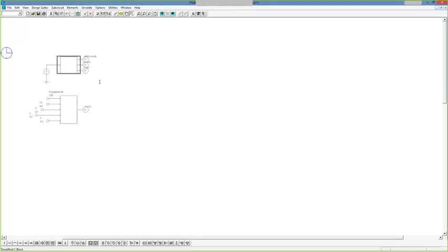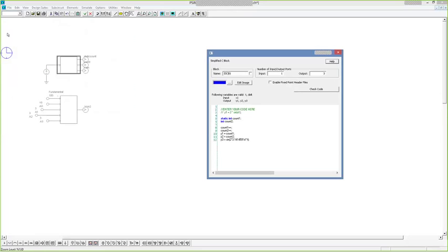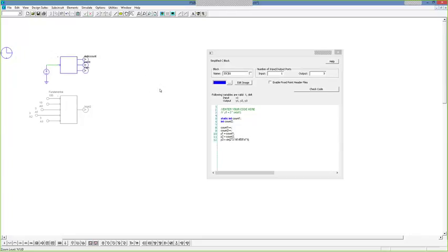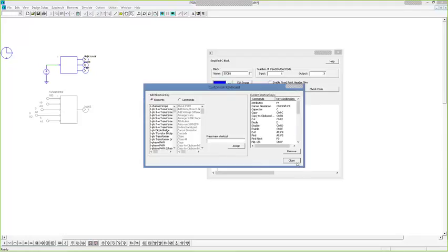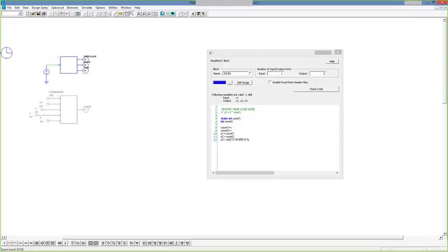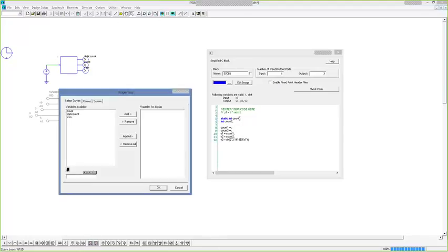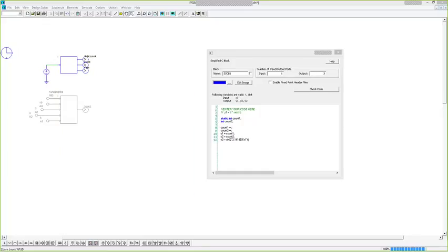So I've got some simplified C blocks right now. I'm just going to enable this. I'm using hotkeys, and to set up the hotkeys, you go to options, customize, keyboard, and then you can define these things here. So I will run this simulation, and you can see I've defined this count variable two different ways, and we can have a look to see what happens. So I define the variable count, and we increment it, and then we display it.